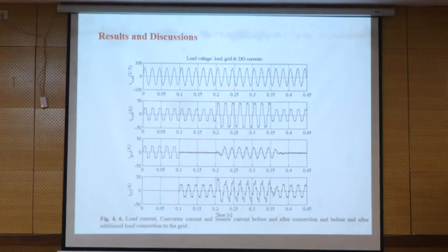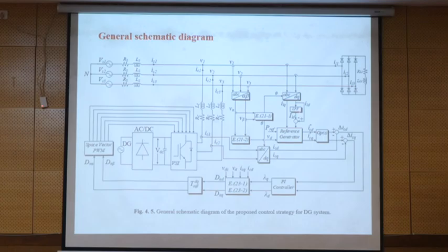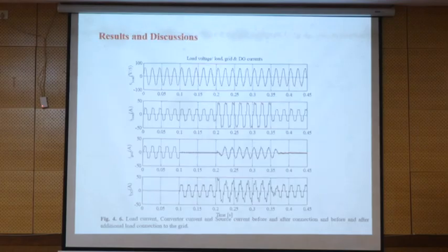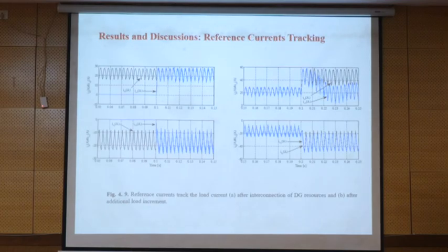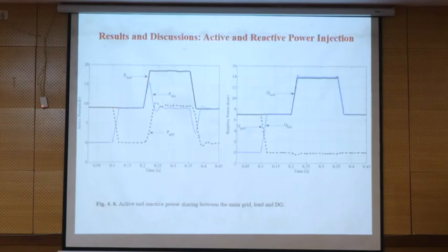If you look at this one, you see that we have a filter in the D axis, but we don't have one in the Q axis. That one is providing this fluctuation. But there is another answer for that. Another reason. Inertia. Also the inductive behavior of the grid. Sudden changes of the current are not supported in the grid.